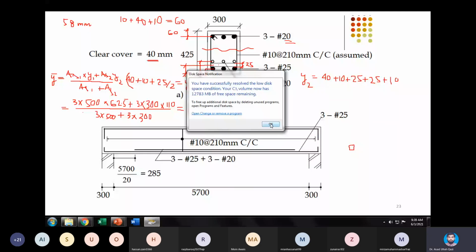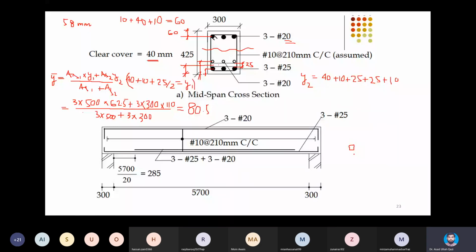In some projects there is a very wrong practice that they use brick ballast or some broken pieces of clay brick to lift up the cage. You know that brick is a porous material, it sucks water, so it will trigger the rusting of the steel bars.